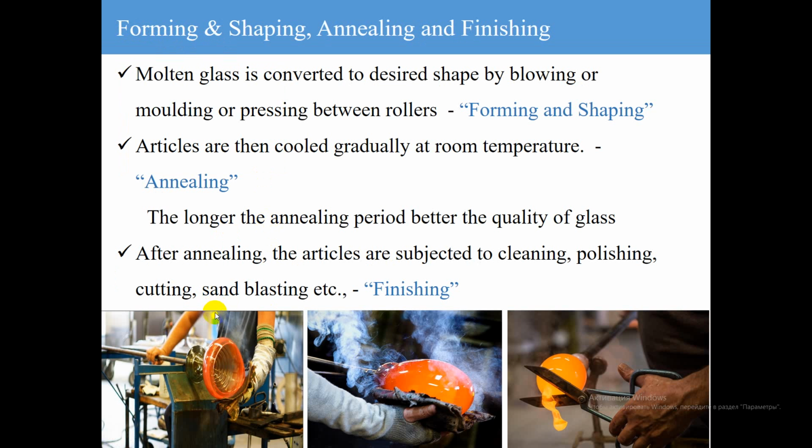It's important to recognize that when heated, glass doesn't melt in the conventional sense. There is no fixed temperature at which glass passes from solid to liquid. Rather, the glass progressively softens as the temperature is raised. This is why glass is sometimes called a supercooled liquid. We can distinguish a number of glass shaping processes.